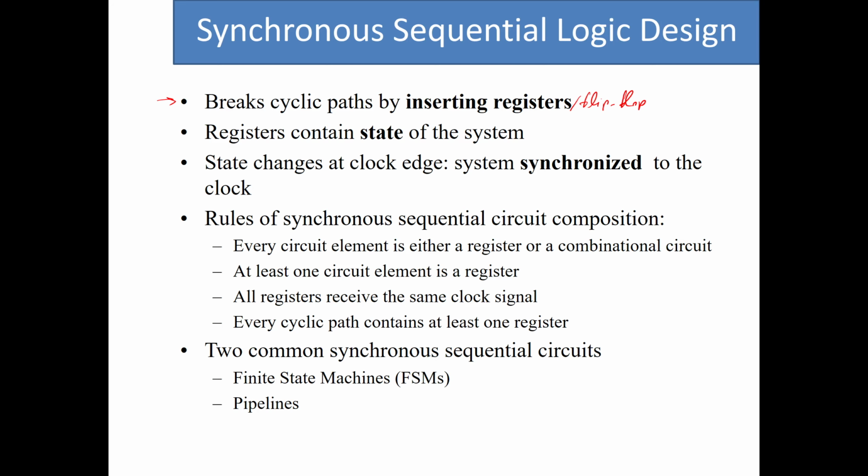Another rule that we knew from before is that registers are there to contain or store the state of the system. So this is not something new. We actually designed the state elements to be able to store the state of a system. The third rule states that state changes only at the clock edges.